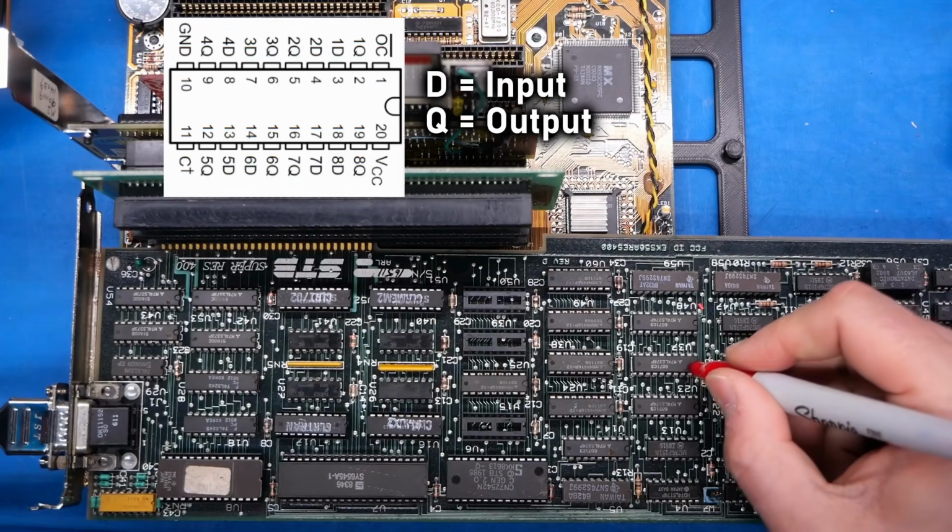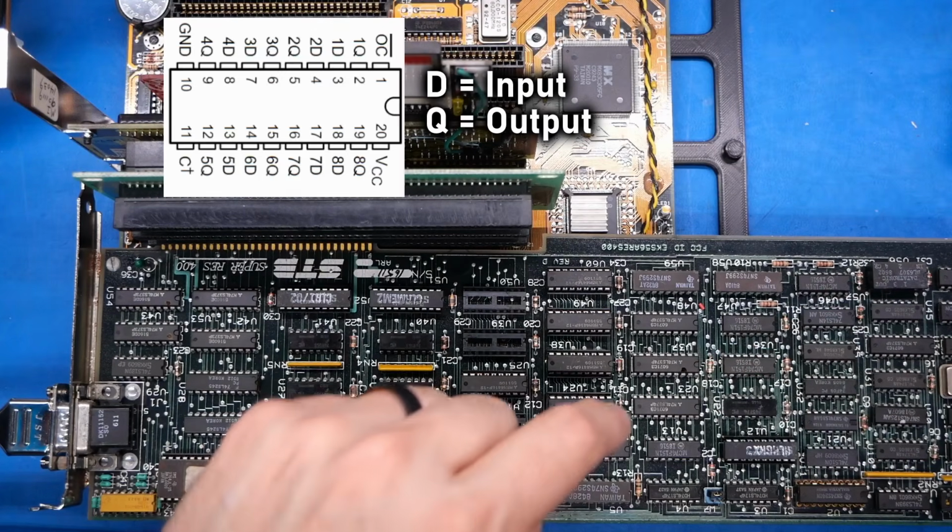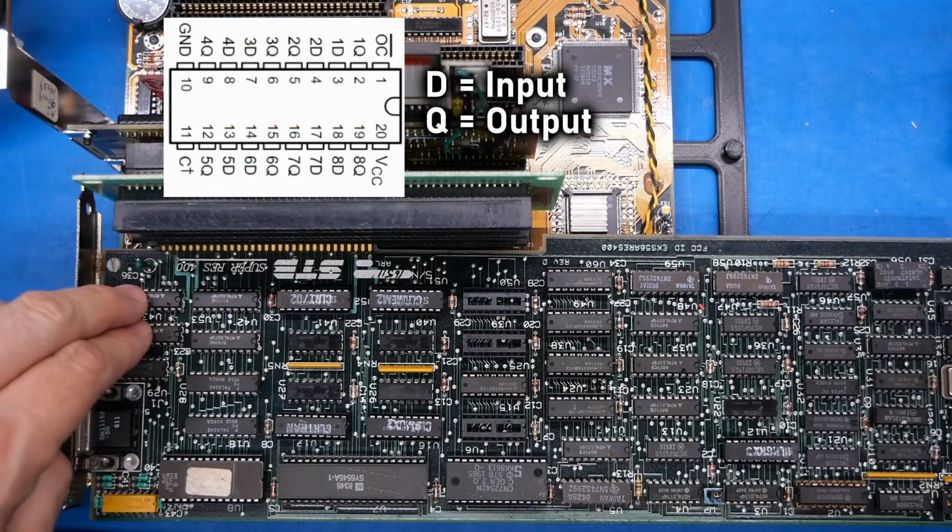We found our two suspects here. It's one of these two chips. It's either that one, or these two. All right, so that's excellent. So we don't need to go removing those from the board and just swapping them all out. What we need to do is hook up the oscilloscope and just start looking at the inputs and the outputs of each of those chips.